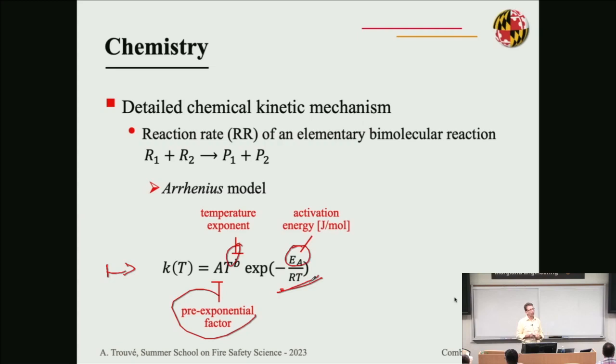But if I raise the temperature to a few hundred degrees C, then this reaction can start, and in that case, it's going to be very fast. So you have a binary dynamics in combustion systems where either nothing happens or everything happens super fast. Okay, it's one or the other. And that's the exponential dependence on temperature that is responsible for this. So that's a feature of combustion processes.